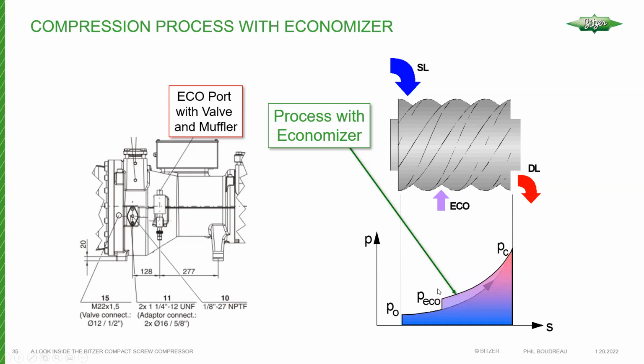And as we know, when you operate a compressor at higher pressures, you'll get more mass flow, and generally speaking, more capacity for every kilowatt that you put into that compressor. So overall, your power input per ton of refrigeration, I'll say, will be less when you do that. So generally, well worth it. When you get into higher temp systems, you really have to weigh out the pros and cons, the costs and what am I gaining for it and all that. But you can economize any system really, or any compact screw compressor based system.